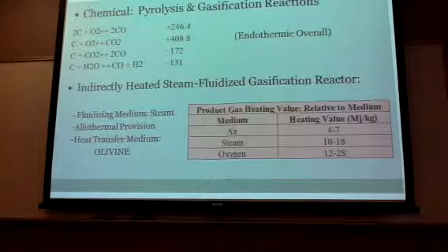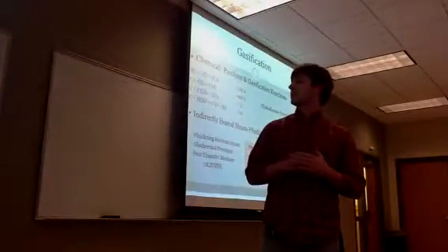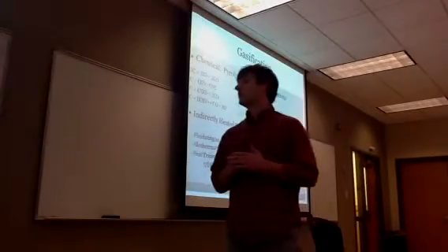And for our fluidizing medium, we chose steam for several reasons. One, air has several noxious byproducts with the increased nitrogen content. And you can see that air produces a lower heating value product, while steam produces a higher heating value.